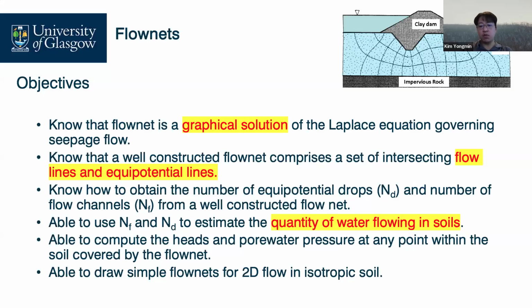In many instances, the water flow through soil is not one direction only, nor is it uniform over the entire areas perpendicular to flow. In such cases, the water flow in soil is generally calculated by the use of a graphic referred to as a flow net.